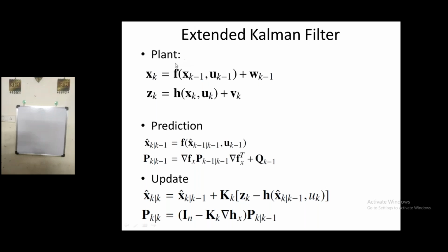So the idea here is, if this is a nonlinear one, nonlinear equations can be expanded by using the Taylor series approximation. In the Taylor series, you can expand this into Jacobian, Hessian, and higher order terms. So when it comes to state estimation, we preserve only the Jacobian terms, and the higher order terms we assume are zero and not considered. And the Jacobian of a particular nonlinear system we represent as delta f by delta x. So this is the Jacobian.